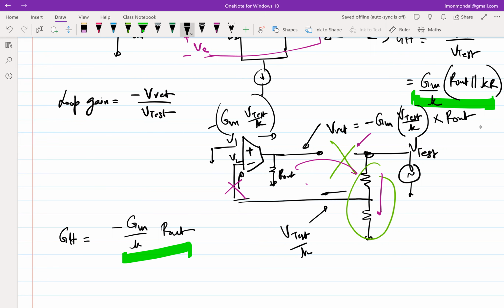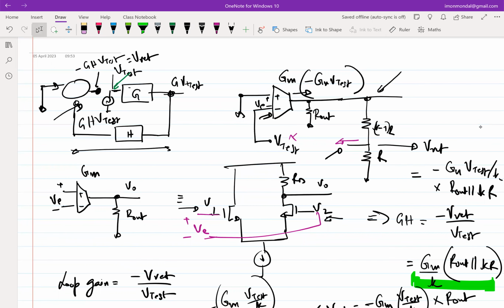No, it was a demonstration to show that, if you have to draw an analogy with this GH plot, the GH block diagram gives you an impression that you can break the loop anywhere for finding loop gain, and it should be fine. But in a more practical scenario, this GH block diagram essentially assumes that H and G are independent of each other. In reality, it loads, right? They are not independent. In fact, if you take more circuit design courses, you will see that neither G nor H are independent of each other. So you always load, and if it loads, then you have to put back the loading in some way and then figure it out.